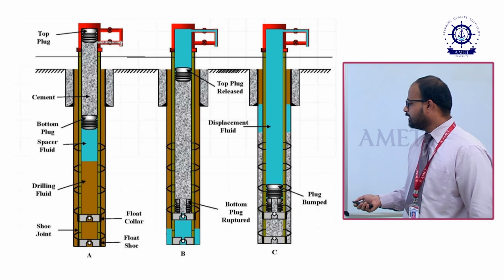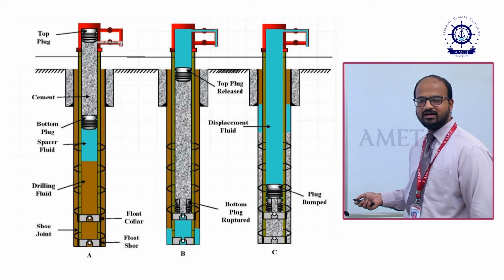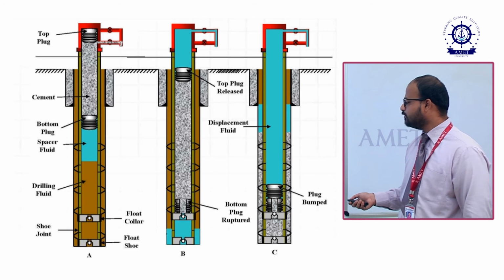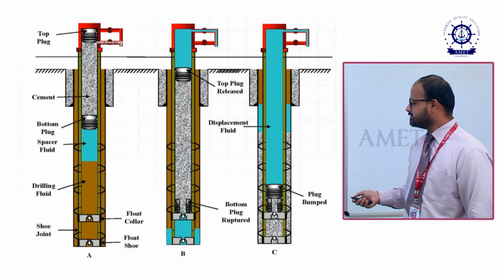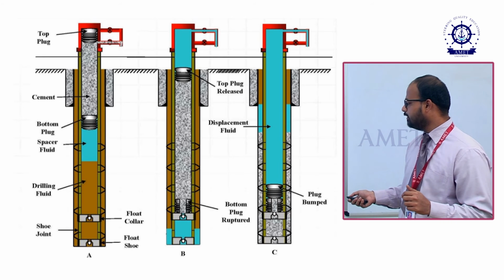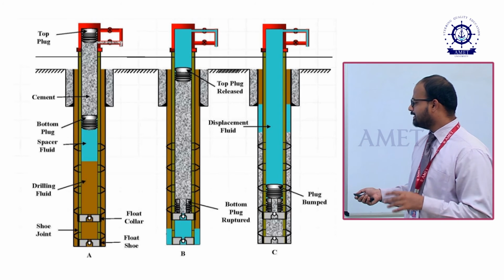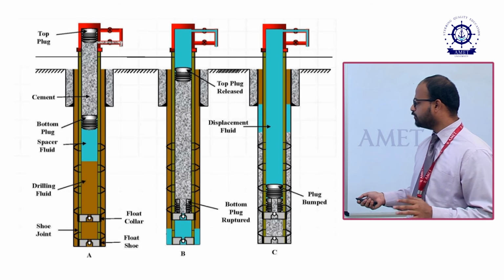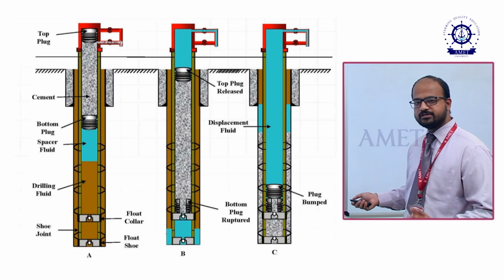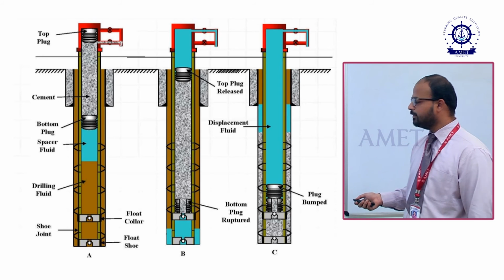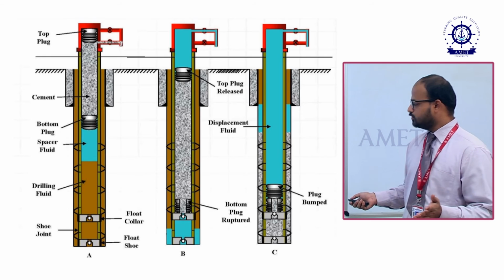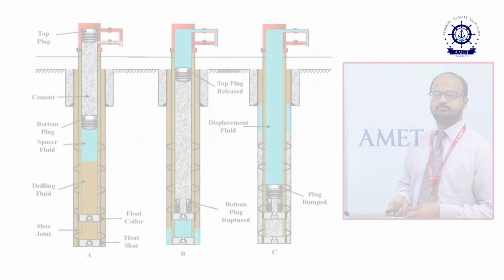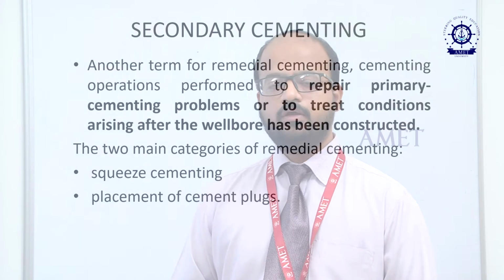If you see the cementing coming to flow back into your well casing or inside your wellbore, then if it is more than 5 bbl, we can understand that the cementing is not done properly. If it is done properly, there won't be more flow, only 2 to 5 bbl. Now that is the procedure we have done for the primary cementing.